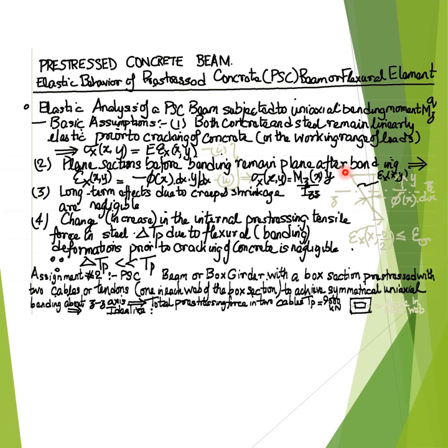In other words, the shear strains are negligible in comparison to the flexural strains, as in case of a slender beam in which the plane sections before bending remain plane after bending, since the shear stresses in a slender beam are negligible in comparison to the normal bending stresses.